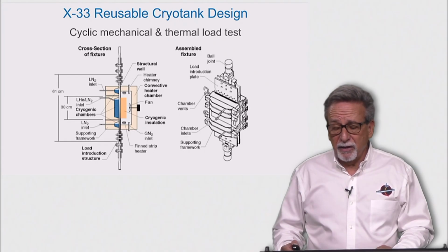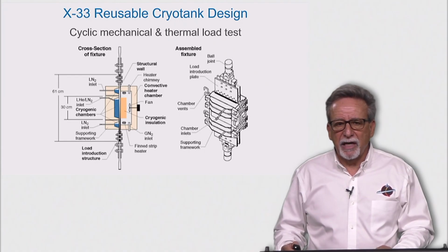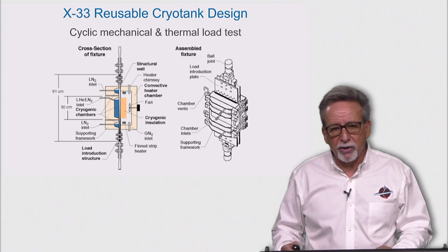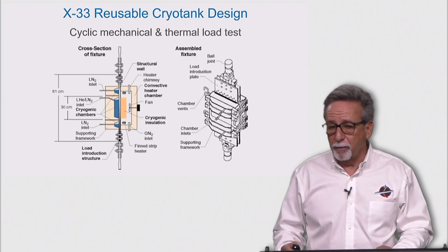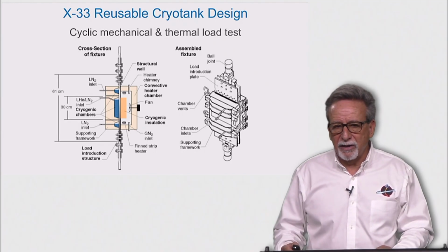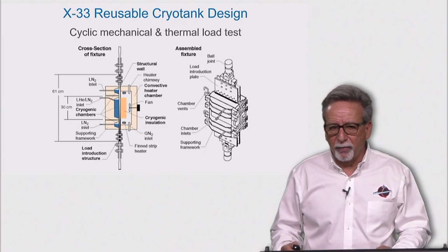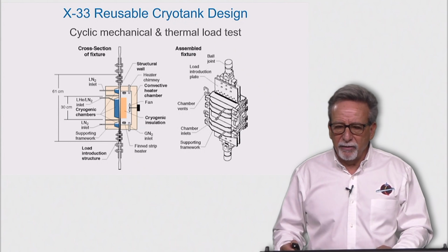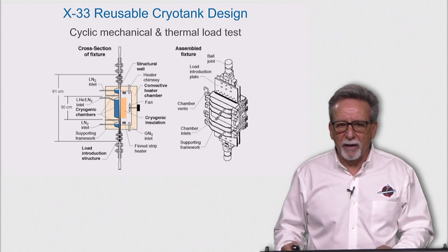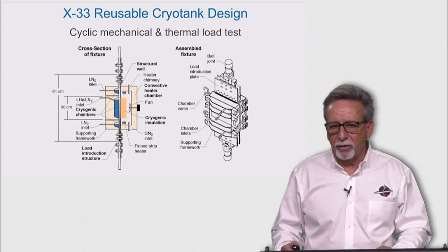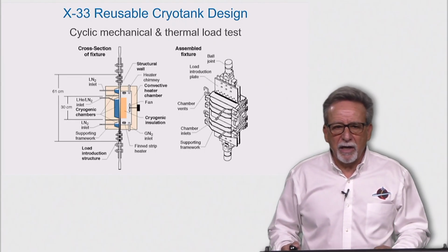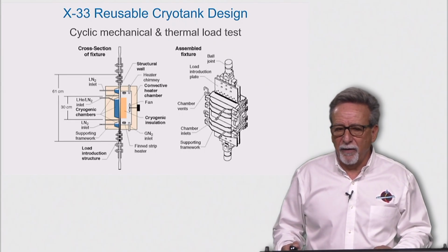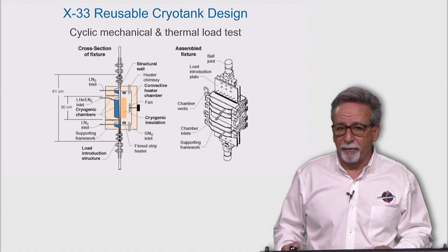And this test fixture was designed to simultaneously apply cryogenic temperatures on the liquid side of the cryo tank and elevated temperatures on the thermal protection side, at the same time that we would apply in-plane mechanical loads. It is very important to simulate the in-plane and combined cyclic loading histories in order to determine the life cycle performance and mechanisms for failure of this particular concept.